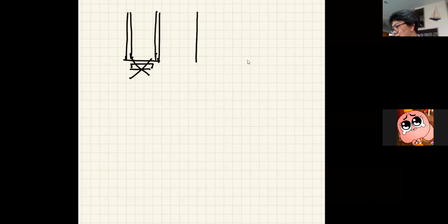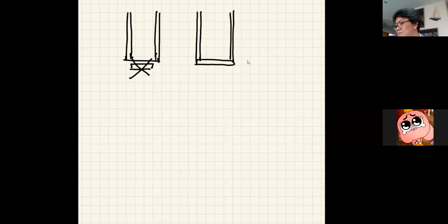Some would say, okay, this is my column and then my base plate, and let's make it equal to the column. How would you connect your base plate to the column? The only means is to weld them, right? So how would you weld the flange of the column to the base plate here? That is impractical as well. Even though you get everything correct and your base plate is not going to fail, the size you decide to use cannot be constructed.